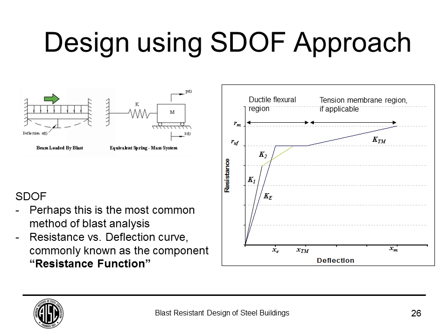In this case, we're developing a single degree of freedom that is tracing the mid-span deflection of a fixed beam. So you turn that into a spring mass system where the mass represents the tributary mass of that beam at this one point, and the stiffness represents the strength, Ru, and K, the stiffness of the actual beam. When you develop a single degree of freedom, generally you have three main parameters that define your behavior: the stiffness, the ultimate resistance, and the mass, and that creates what we call the resistance function. So you can see it right here.